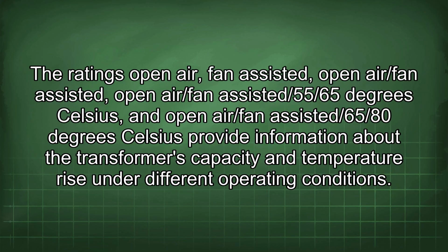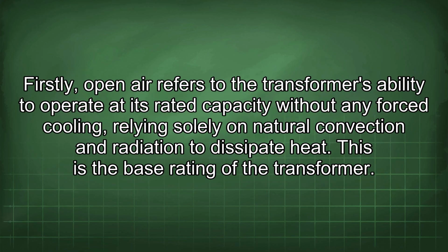The ratings open-air fan-assisted, open-air/fan-assisted, open-air/fan-assisted/55/65 degrees Celsius, and open-air/fan-assisted/65/80 degrees Celsius provide information about the transformer's capacity and temperature rise under different operating conditions. Firstly, open-air refers to the transformer's ability to operate at its rated capacity without any forced cooling, relying solely on natural convection and radiation to dissipate heat. This is the base rating of the transformer.